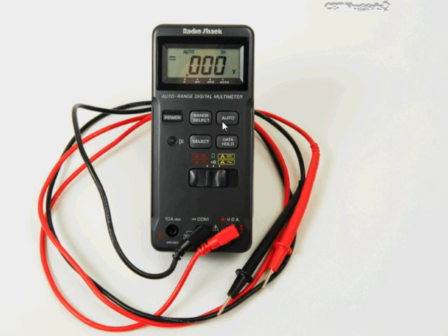One of the things you also want to make sure you do is, don't get your grandfather's multimeter, because he may say, well, I've got one that has a little needle on it and it just kind of switches from left to right. Don't use those, because what those do is they actually backfeed 9 volts into the circuit in order to do their testing, and that can be bad for electronic components that we use nowadays. So for computing purposes, don't use any of those that have the needle that swivels from left to right, like a gas gauge looking thing.